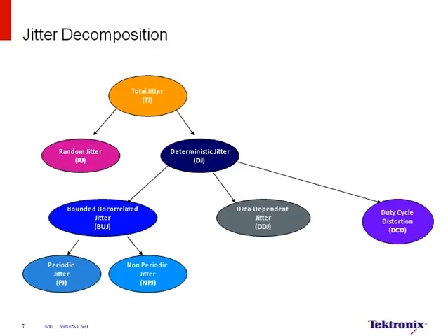So in the same sense that the receiver has a loop bandwidth, it's got a PLL peaking factor. It's also got, what's the third one here? A PLL order. What you're trying to do in the scope is that you're trying to make the scope behave like the receiver.